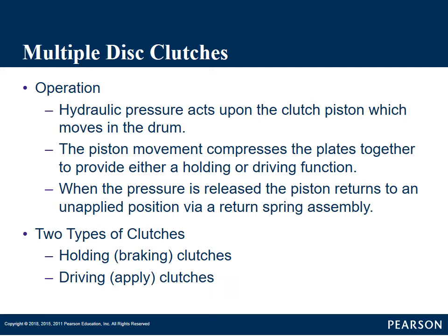So we can look and say, this thing's slipping in 2nd gear. What clutch is supposed to be applied in 2nd gear? So I could know which direction I should be looking if I'm going to take that apart, what I should be finding in there if something's burned up. Or it might lead me to maybe a shift valve not moving. But we'll talk about that more when we get into the diagnosis.